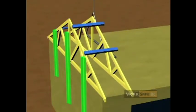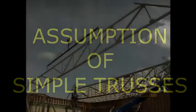The loads are applied to the truss at the joints only. The loads lie in the plane of the truss, and each load does not produce bending or torsion in any of its members. Assumptions of simple trusses.